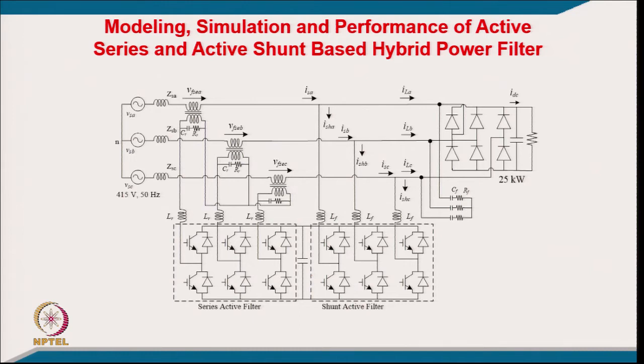This is similar to what we discussed already for UPQC, but you can understand the difference between UPQC and this active hybrid filter: we assume that you have harmonics in the load current and voltage harmonics in the supply voltage. So, this load really needs good quality voltage at the point of common coupling, so that the load is not disturbed, as well as a sinusoidal supply current. So, this will be able to give good quality in both cases.